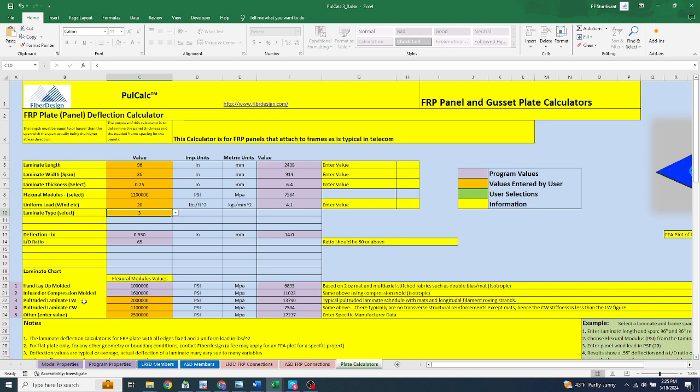We have to remember that in the pultrusion world, the lengthwise and crosswise strength factors are very different, because the fabrics that provide most of the strength tend to run mostly in one direction. So if that means something for you, then you want to pay attention to that.